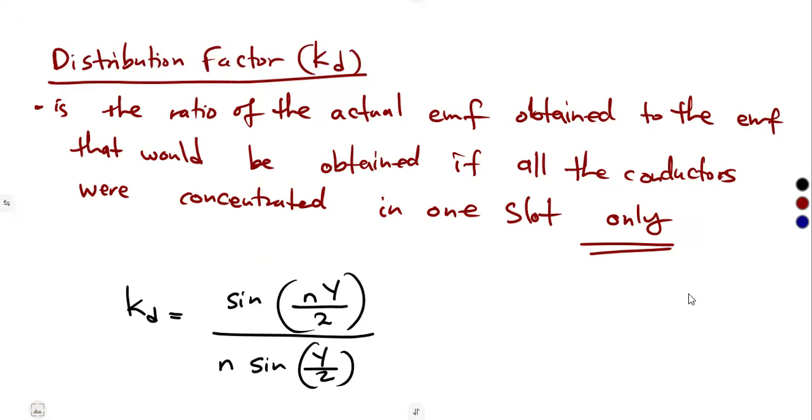From our formula sheet, the gamma that we are seeing, they can give you this as angle alpha. They use alpha, like this. It's just one and the same. Your textbook might be using alpha, maintain that alpha. Your textbook might be using gamma, maintain the letter gamma. They can use any letter. Maintain the letter that you're given. In this case, this N here represents the number of slots per pole per phase.